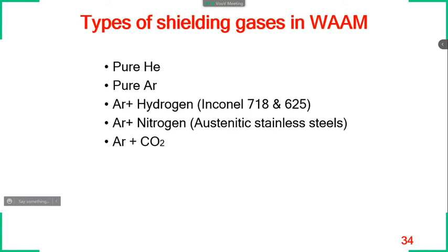Austenite is a highly unstable phase, especially during solidification, and some retained ferrite may come. So in order to make a greater volume fraction of austenite, we will add nitrogen to the mixture. This nitrogen will stabilize the austenite phase so that there is more austenite and less ferrite. Why? If the ferrite is increased, what will be the problem?